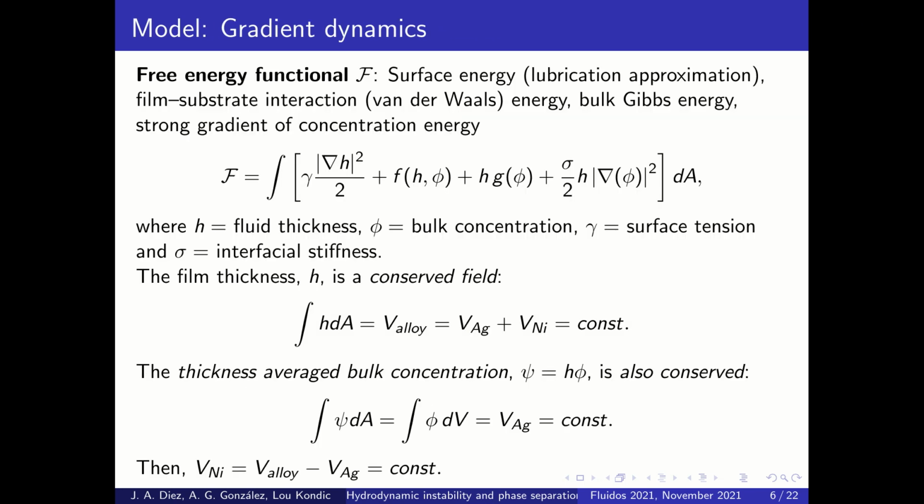So from the modeling point of view, we start with the free energy functional, which includes all the energies at play in the problem: the surface energy within the lubrication approximation, the film-substrate interaction through the van der Waals forces, the Gibbs energy of the problem, which depends on the concentration of each metal, and the energy due to the strong gradients that are produced when you have separation of the metals.